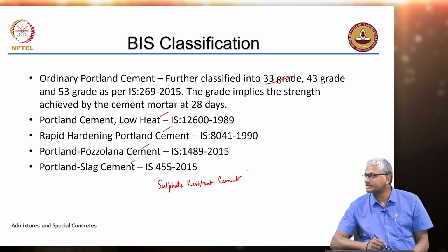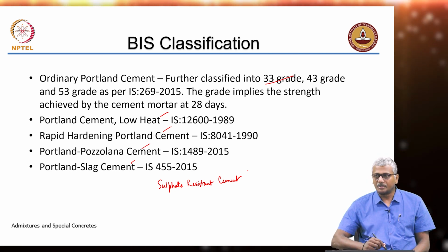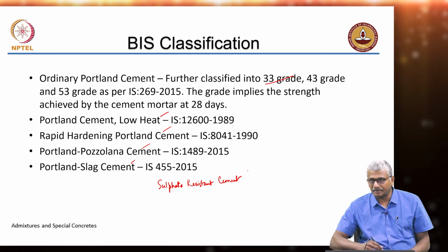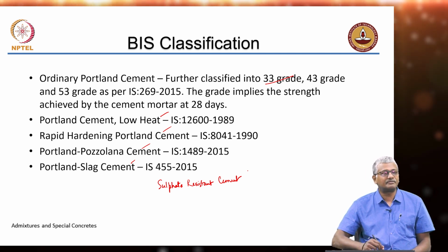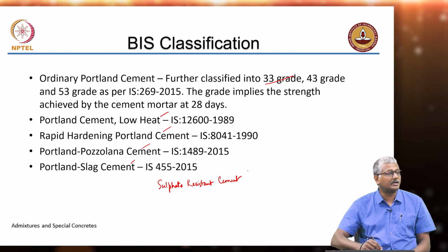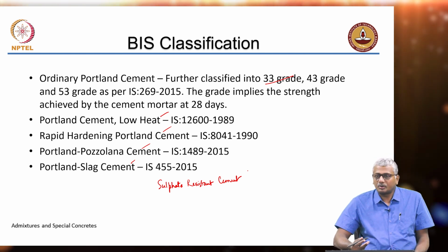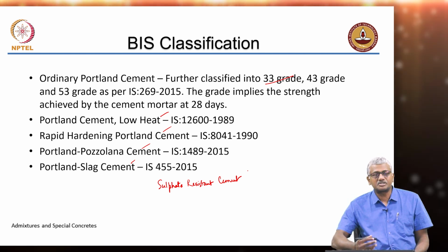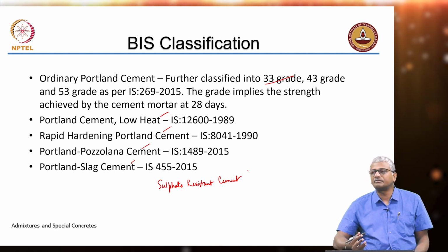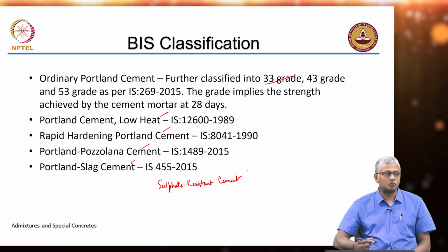Okay. So, like that we need to make do with mineral additives whenever we need special properties, like high early strength for instance. If rapid hardening cement is not available or is not very practical to be used, because it may also start setting very quickly, it will reduce the time that you have for concreting. Like in Mumbai, you know, right, we have high rise buildings where people are using even M90, M100 grades of concrete. In such cases, imagine using a rapid hardening cement, you will never be able to maintain workability. Okay. In such cases, what comes to benefit of the concrete producer is the use of fine additives like silica fume or metakaolin, about which we will learn more detail later.